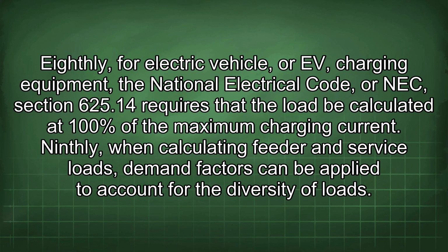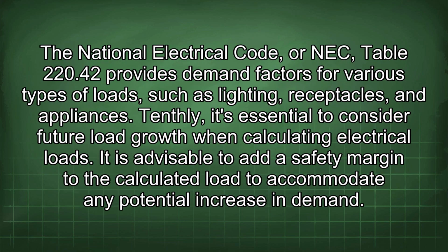Ninthly, when calculating feeder and service loads, demand factors can be applied to account for the diversity of loads. The National Electrical Code, or NEC, Table 220.42 provides demand factors for various types of loads, such as lighting, receptacles, and appliances. Tenthly, it's essential to consider future load growth when calculating electrical loads. It is advisable to add a safety margin to the calculated load to accommodate any potential increase in demand.